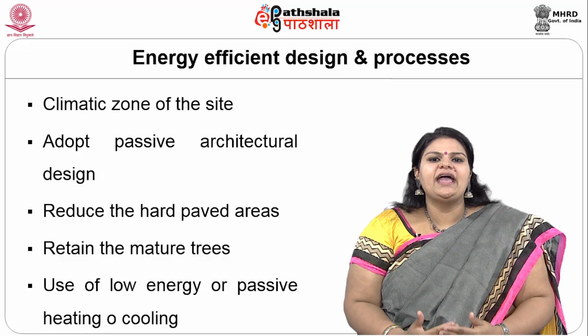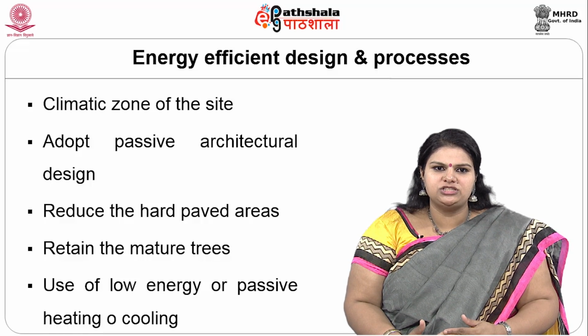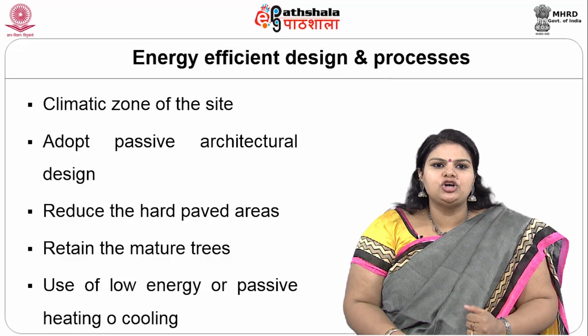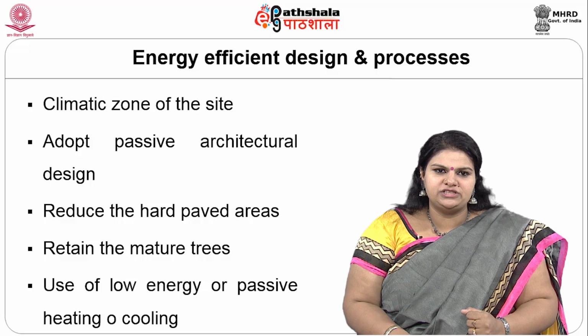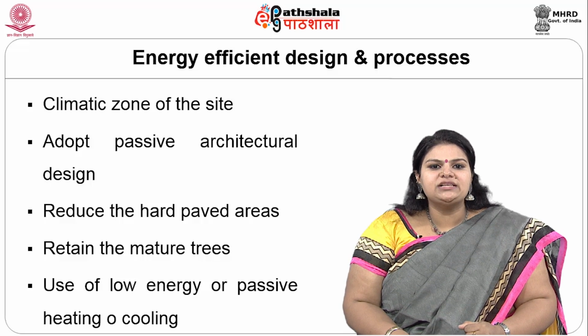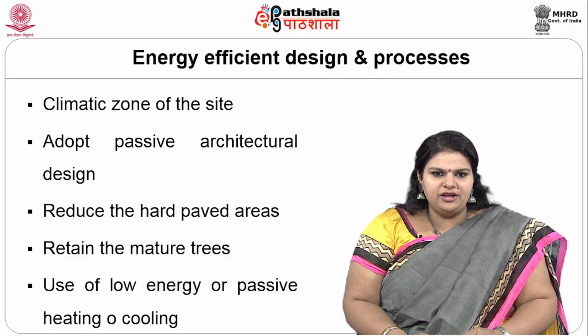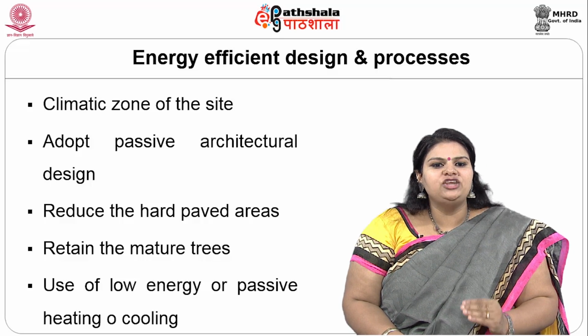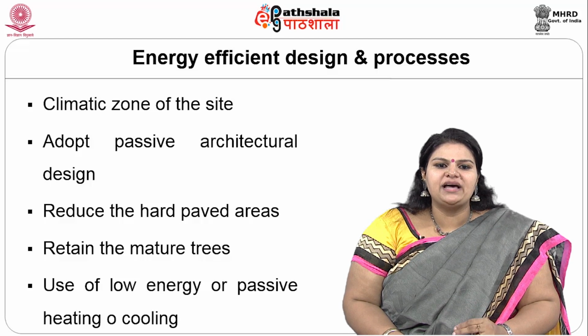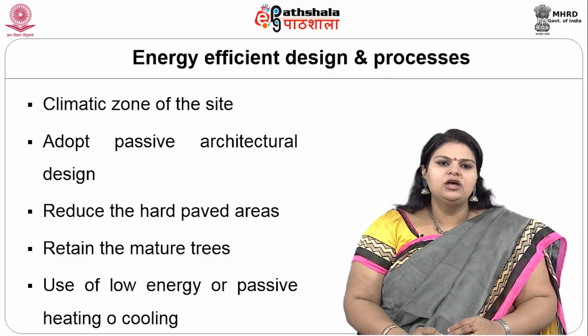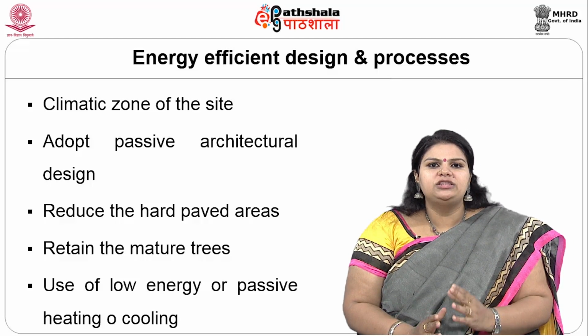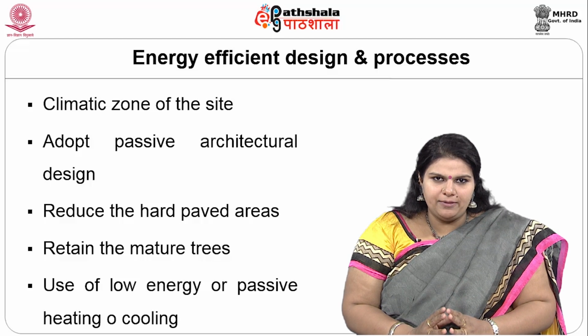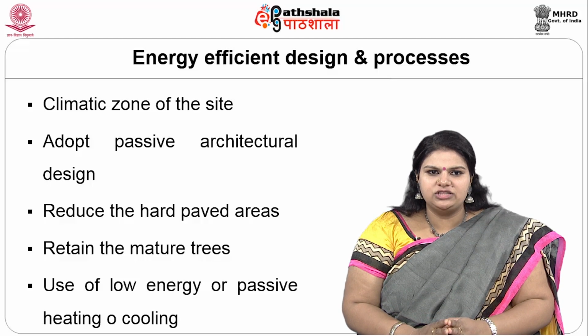So if we look at energy efficient design and processes, we have to make sure we have the climatic zone of the site. We need to adopt passive architectural design, reduce the hard paved area. We need to retain mature trees and use low energy or passive heating or cooling. So whichever climatic zone that place is in, we keep that into consideration.